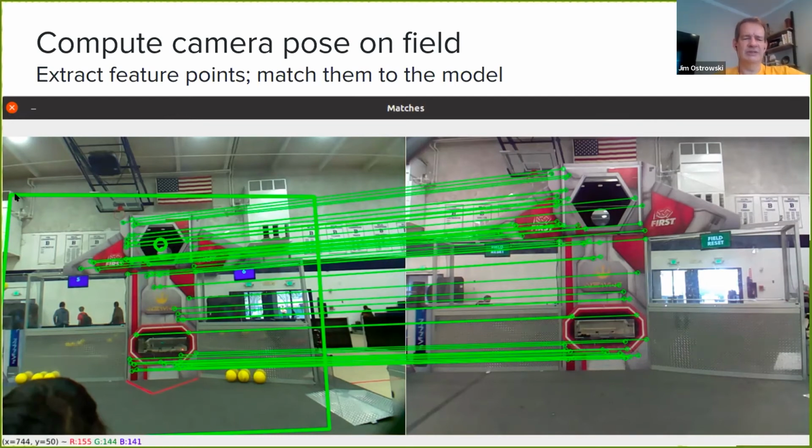I'll just mention real quickly, these boxes are basically transforming where the robot thinks the outline of this image would project to in this space. You can see it's not perfect, but the idea is that it gives you a rough sense of where things are. And this circle here we just drew on for reference is a projected point from the center of the target, just to see that we're tracking properly. So this is just a visualization tool that we wrote to help with this.